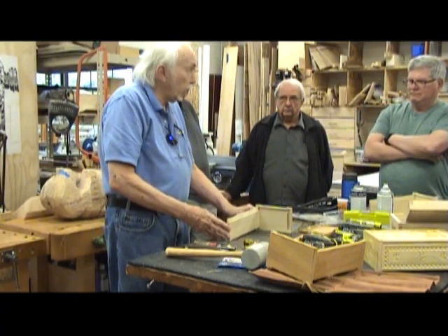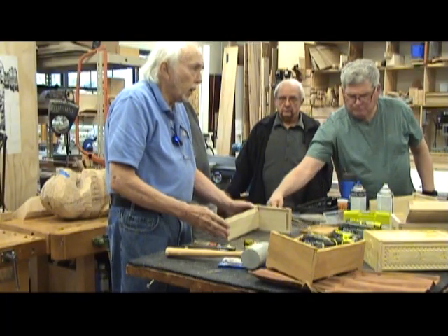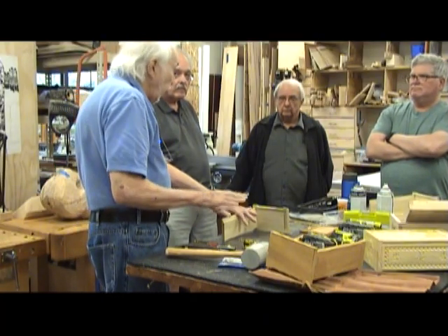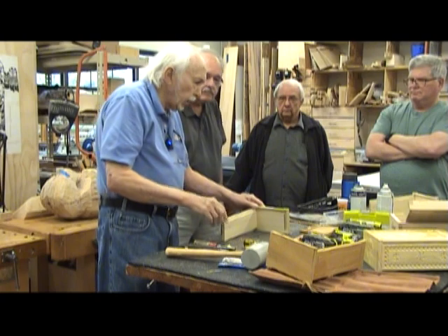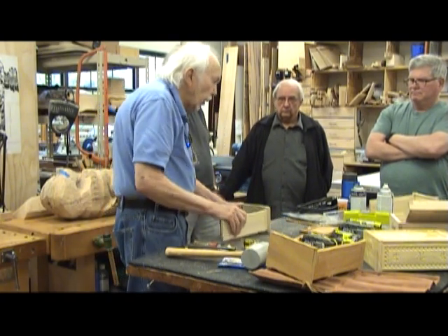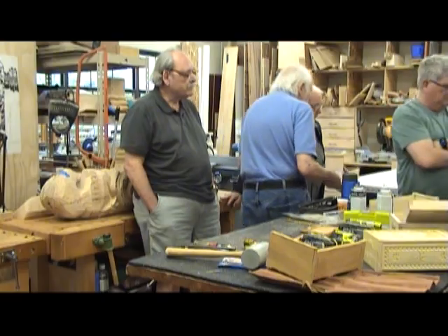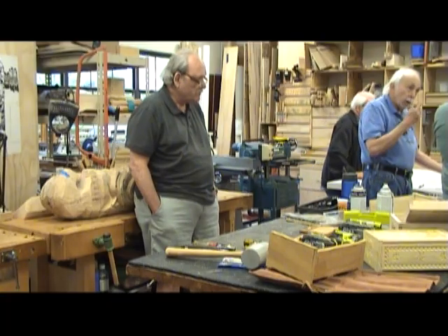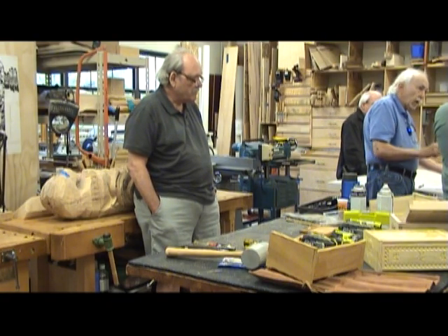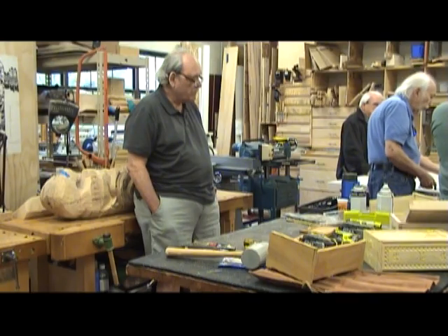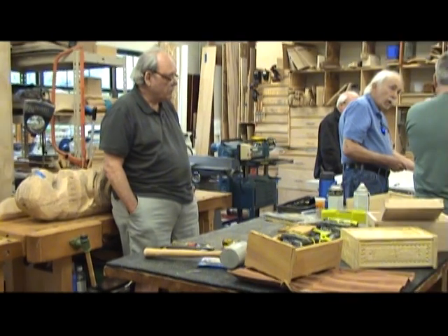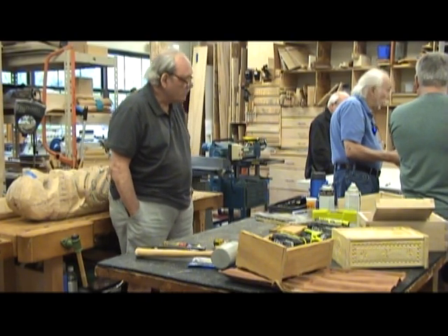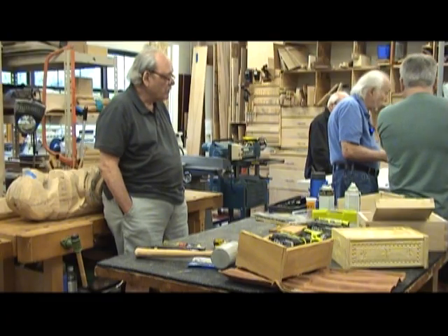Because we have very tight joints, you really don't need a lot of clamp pressure. You just want to hold the box in place. And I would recommend that once you get the box assembled, you take it over to a flat surface here and make sure it doesn't rock. The warped wood or slight imperfections in the fit could cause it to rock. Get rid of the rock in the clamps if you possibly can.